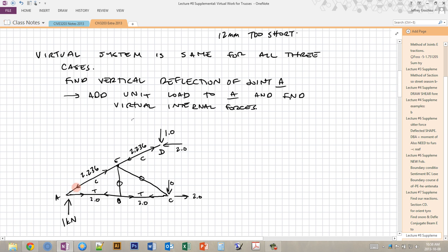So the convenient way to draw these arrows is to draw them with respect to which way they act on the joint, because then you can do this method of joints without having to draw each joint individually, because we have a little equilibrium set up at each joint, where we have this external load, for example. We have this tension load pulling to the right, and we have this compression load pushing down and to the left.